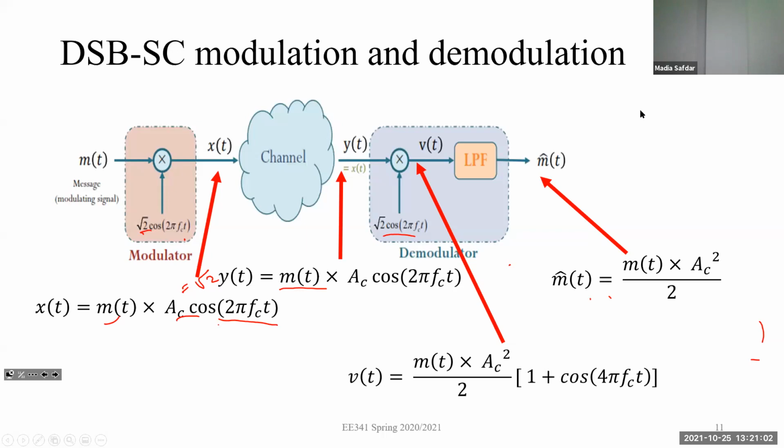So you multiplied it with the demodulator, again at the carrier frequency, and then you passed it through a low pass filter, and at the output you receive this. Then you can see that this is lost now. This is removed now. Okay, this was our carrier. This is removed, and then your actual signal is here. This is removed by the low pass filter, because it's now high frequency. It is removed because it had the constant frequency. So I will apply the filter exactly at the carrier frequency. This will be removed, and then your message signal will be.